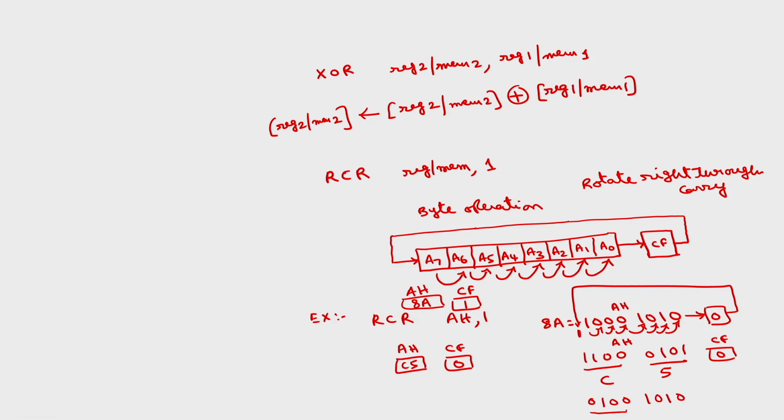So, this content becomes 4A. The contents of AH become 4A and the carry flag will be reset in both the cases.